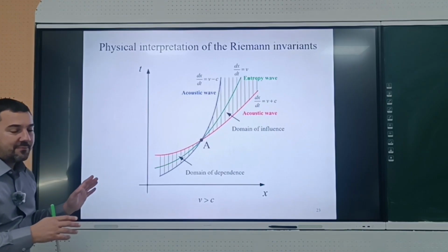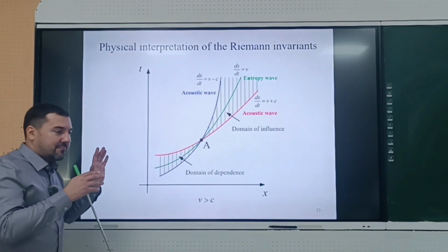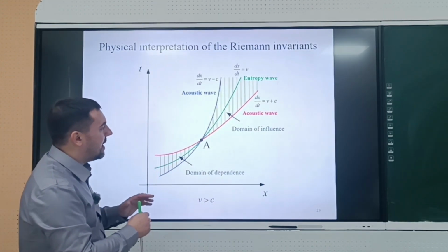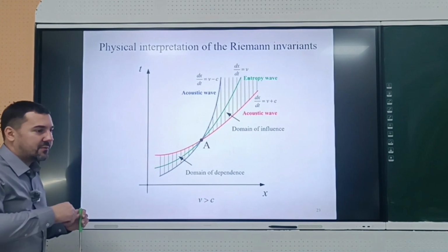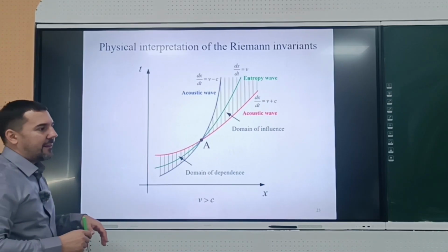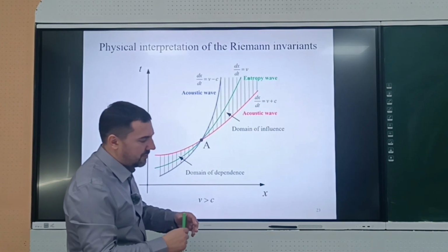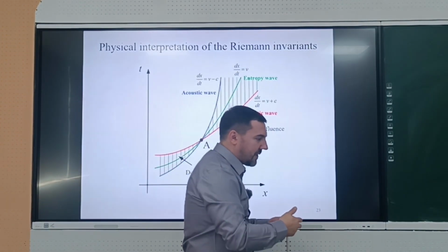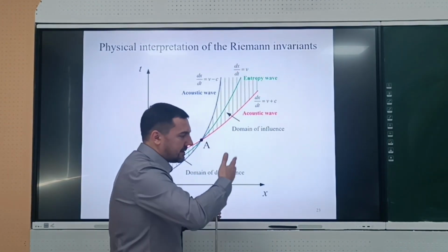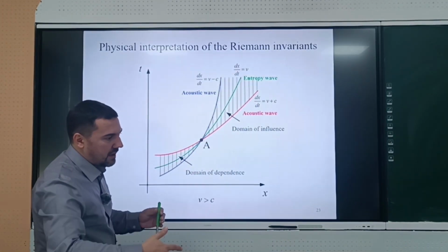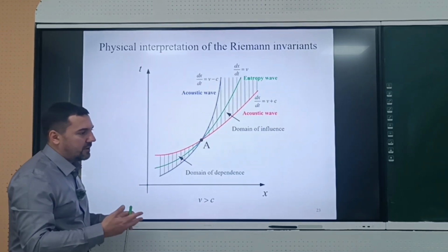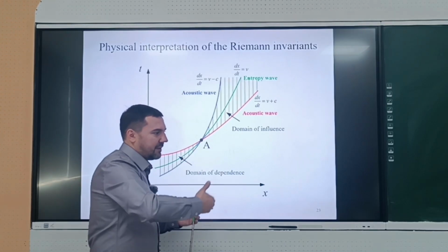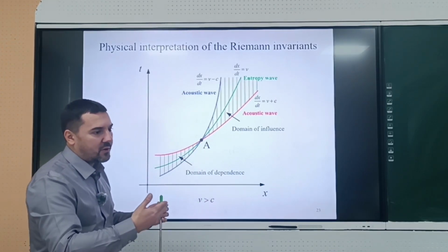So it's a very complex problem. That is why there is some art in how to impose boundary conditions. For example, if you have a subsonic flow, what's the problem? For example, you compute some duct or some part of your engine, and in reality, you do not have open boundaries. You have walls or something like that, but you're not able to compute the whole device. In your simulation, you should use some planes in which you provide some inflow boundary conditions.